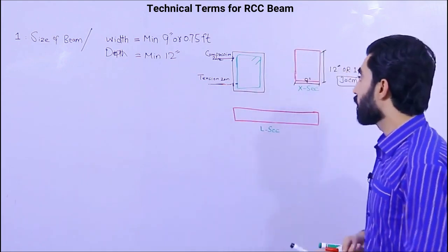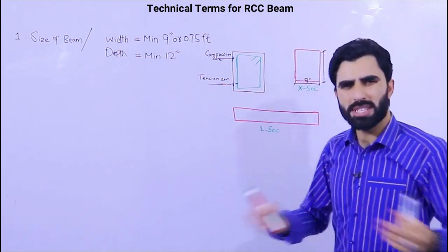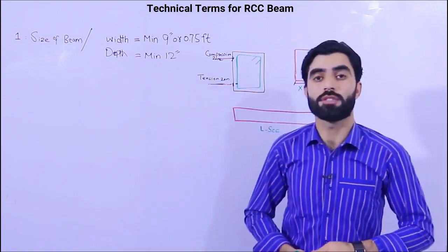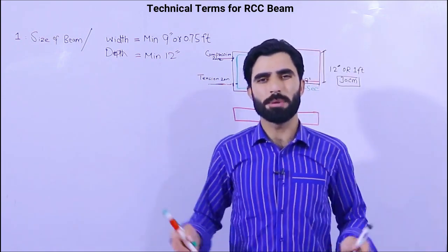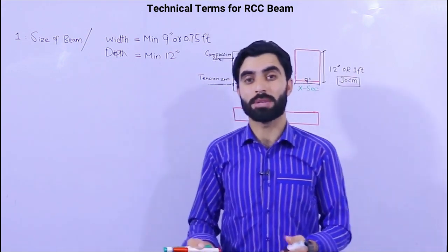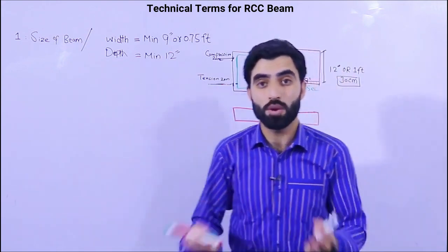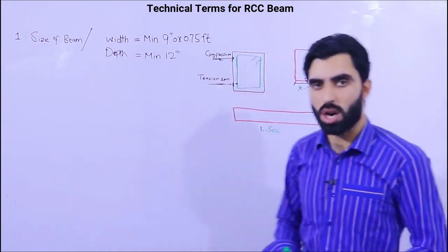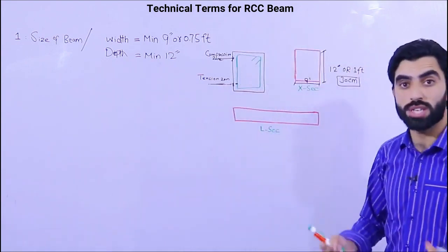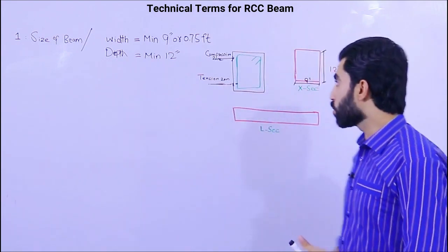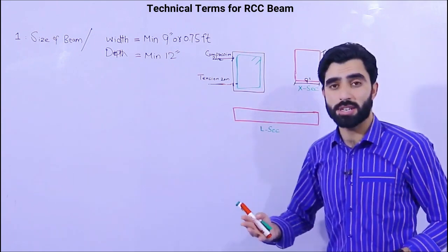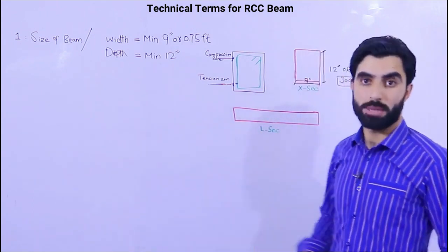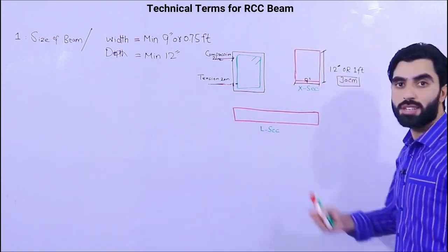Normally if you see in a village, or where there are no rules and regulations for building construction, people are using for G+1 story, sometimes G+2 story, just 4 steel rods of about 10 millimeter diameter. So guys, this is wrong. Don't destroy your building and don't waste your time and money. Be careful with steel structure design, because a plinth beam is very important for the building, and the top beam is also important to resist cracks, etc.